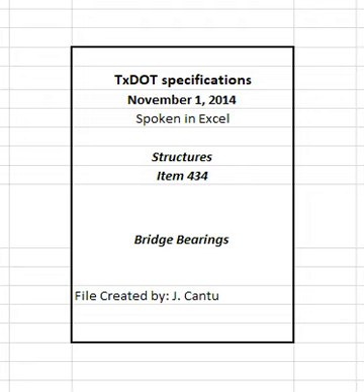TxDOT, Part 3 Adhesion Test Method 3. Bond failure between the PTFE faced steel plate and the laminated elastomeric bearing pad must occur as stated in this test method to constitute a passing test result. Costs associated with testing sliding elastomeric bearing lower component project samples failing to conform to these requirements are borne by the bearing manufacturer. This cost will be assessed at the rate established by Construction Division at the time of testing.